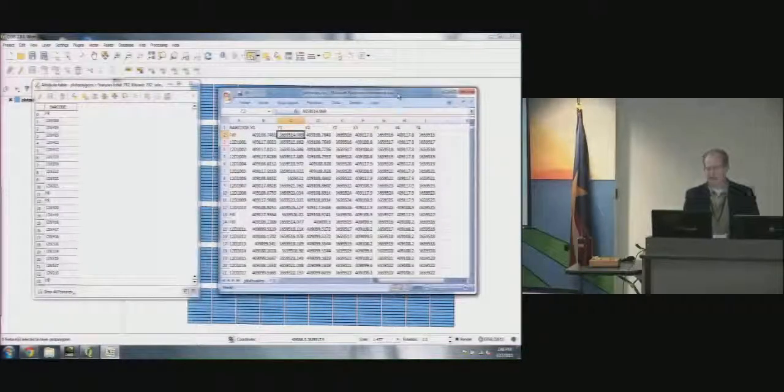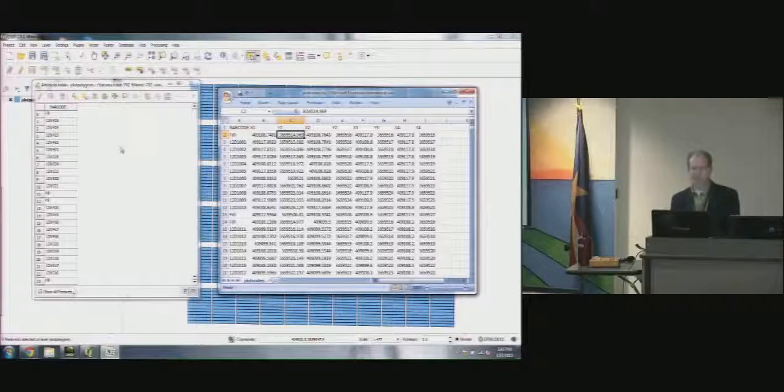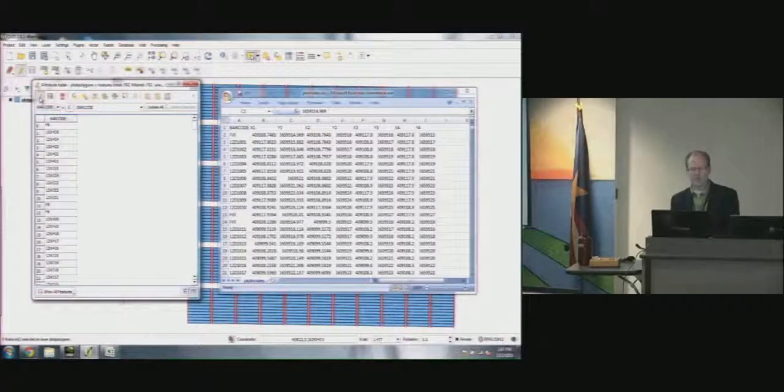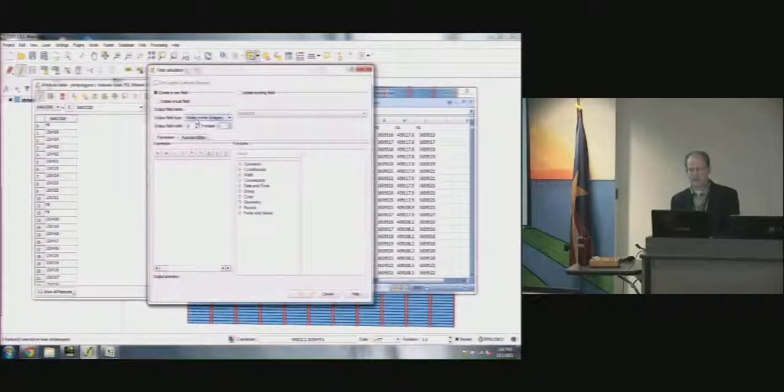So the GIS essentially used the XY coordinates here to draw out the polygons, the shape of the plot, and this barcode information was put into the attribute table for that particular plot. Then you could go in and edit this attribute table however you see fit. You would toggle editing, and you can add new columns and put other data into the attribute table as you see fit.